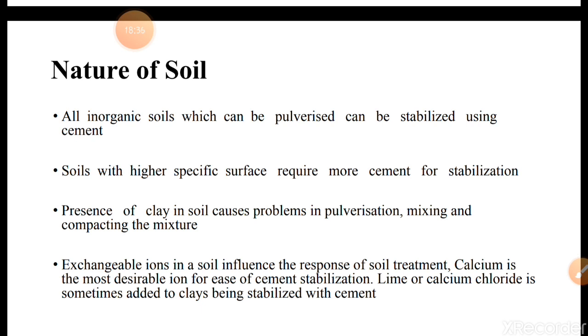Presence of clay in soil causes problems in pulverization, mixing and compacting the mixture. If clay content is more in the soil, there will be a problem of pulverization. Once we mix, it will not be a proper mixture, and once it is not mixing, then it's difficult to compact the mixture.